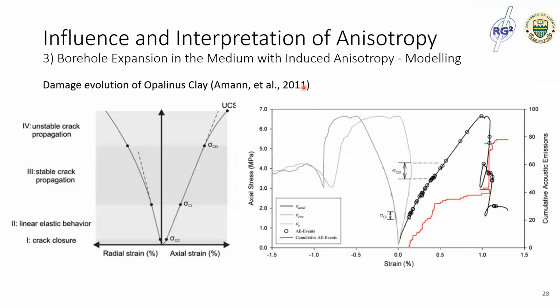That's also a great observation. As you can see, when the stress reaches the peak stress here, we have a very sharp reduction of the strength, and then it goes into a plateau at the post-peak stage. If you look at what happened in the sample, this moment is actually when the rupture plane was formed.